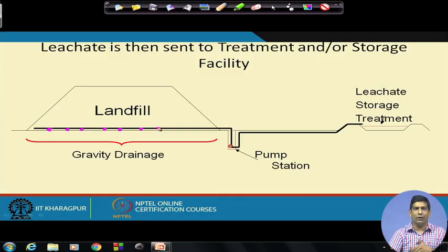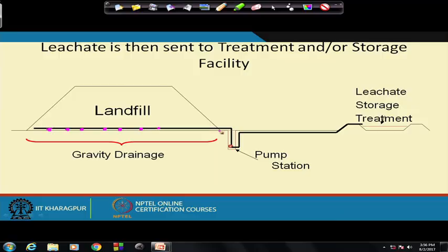If you look at the cross section of the landfill, and you are at the edge of the landfill, the landfill is over here, and all these pipes are coming into what is basically my header pipe. Pipes are joining here, here, and here, and that's how it gets into this header pipe. There is only one place where it comes off from the liner, only one point where the pipe has to come out of the liner.